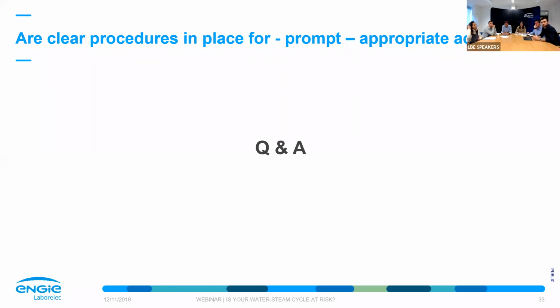Next question, and I hope again I interpret this properly. Is HRSG preservation with ammonia and under nitrogen capping and DO measurement acceptable? Meaning by that we are considering without hydrazine addition. Yes, it's recommended until a certain level. It depends also on the time that you will be in shutdown.